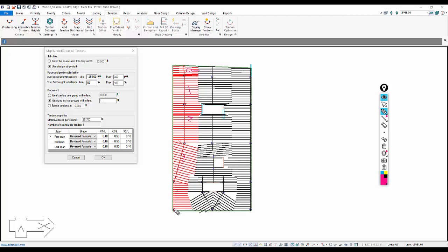And then this tiny little span here will be actually cantilever bottom. So because I input the points like that, or the generation using the wizard input those as such, we have to deal with the fact that there's going to be a tendon span at those locations. But that's easy to deal with. We'll show how you can modify that fairly rapidly.